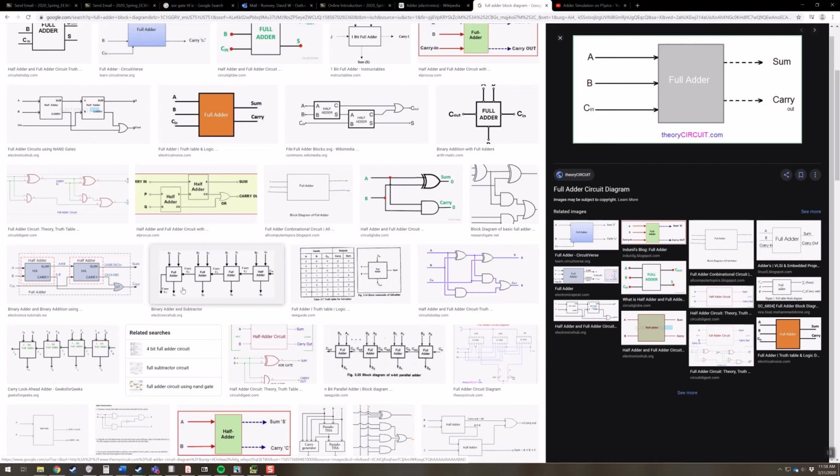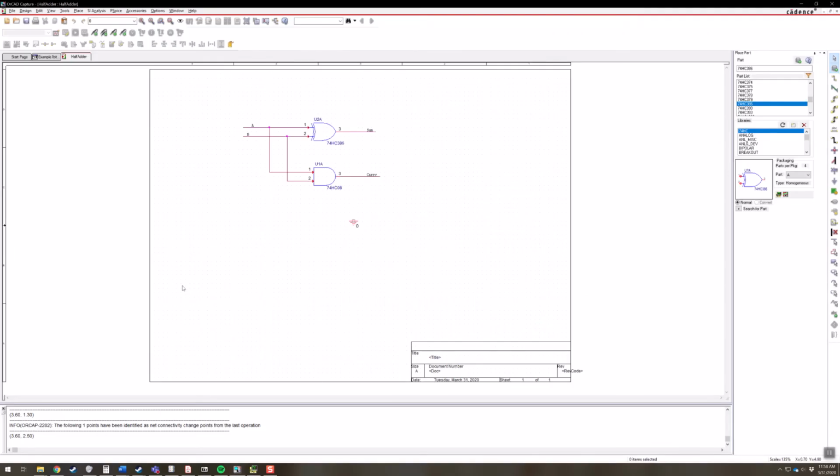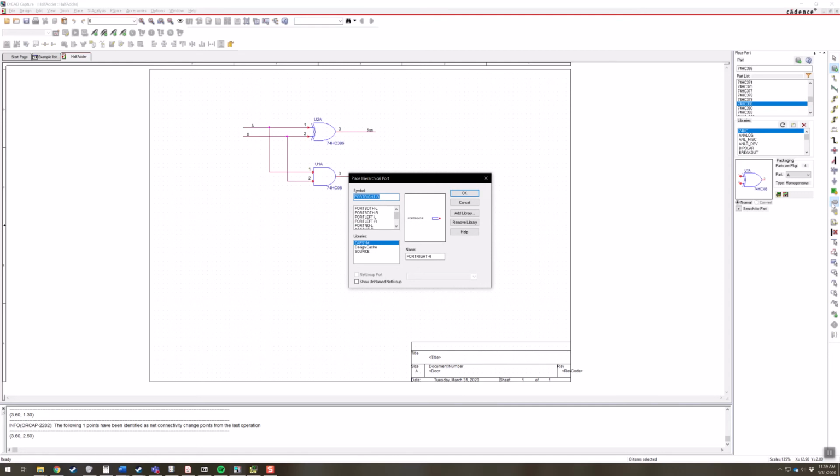So you see, this is how these hierarchical blocks are going to help us. Instead of having to redraw all these gates all the time, we're just going to make one and say, okay, this is how you build a half adder. And then I'm going to have a block for a half adder. And what we need to do in order to do that, you guys would be laughing right now because I'm waving my hands all over the place, is we need to place ports here.